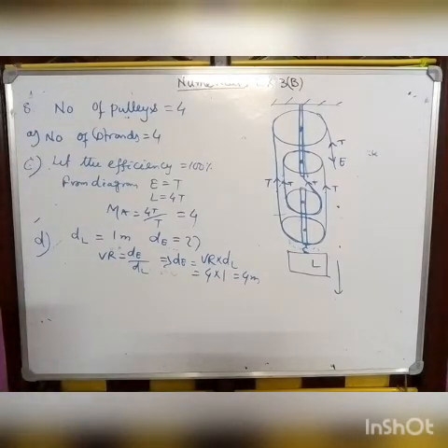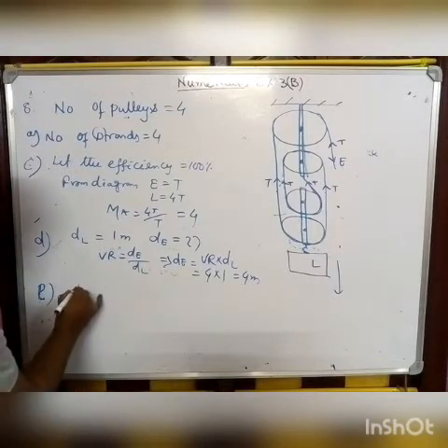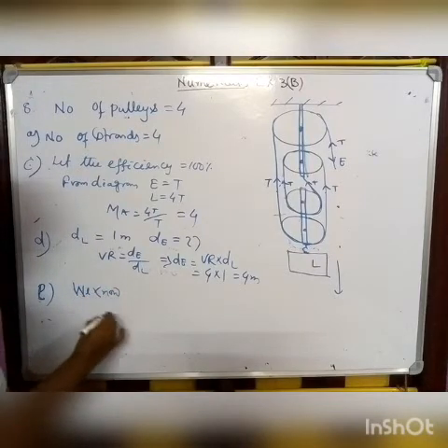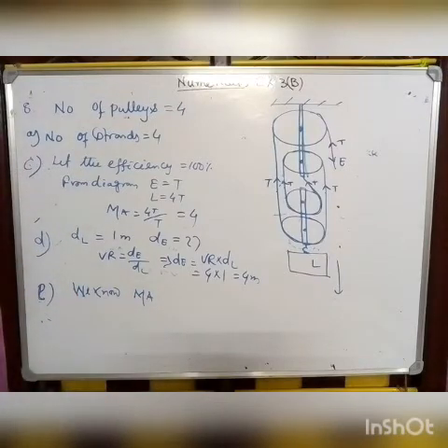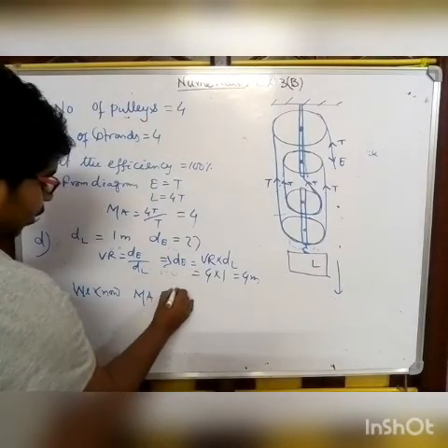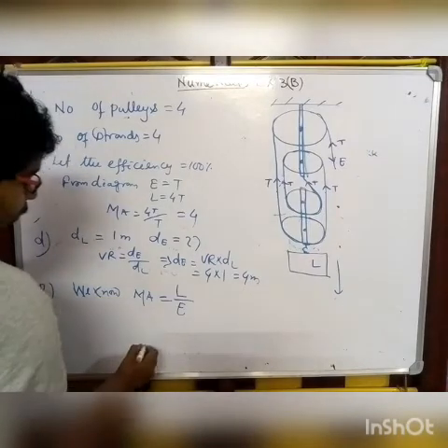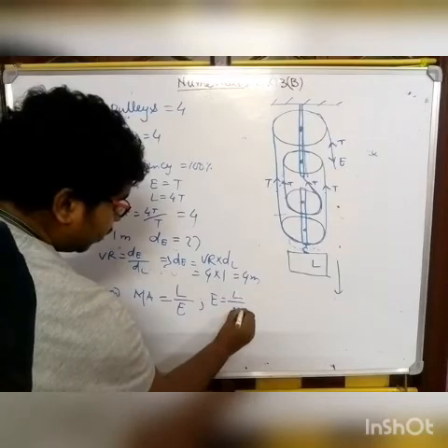How much effort is needed to lift a load of 100 Newton? Next. Okay, so it's question number E. How much effort is needed? We know mechanical advantage. So when it is told about effort or load, we'll just calculate it by mechanical advantage. We know mechanical advantage is equal to load by effort. So here, if I want to find out the effort, that will be load by mechanical advantage.